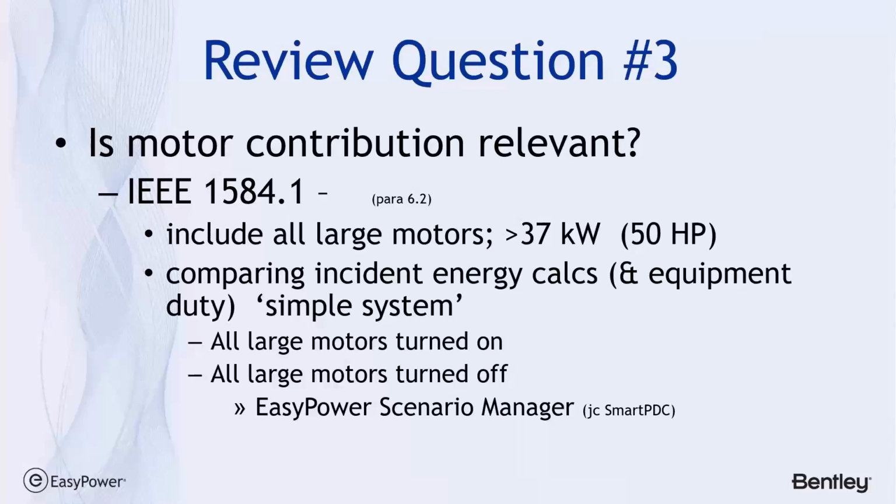Okay, next question. Is motor contribution relevant? According to IEEE 1584.1, which is an application note, your study should include all large motors, especially those greater than 50 horsepower, and then compare incident energy calculations and equipment duty, comparing all motors turned on and all motors turned off.